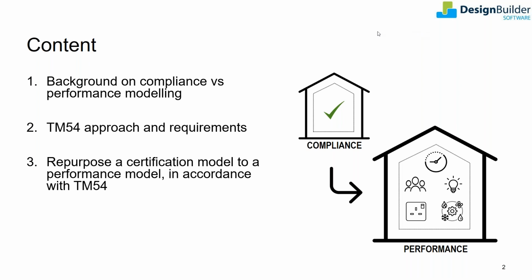After that, I will explain the TM54 approach to modeling and its requirements. And in the simulation software, I will demonstrate repurposing of a certification model to a performance model in accordance with TM54 guidelines. Through this process, I will explain to you the various calculations and results that can better explain the building performance and enable informed design decisions.